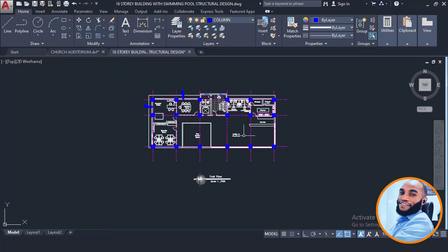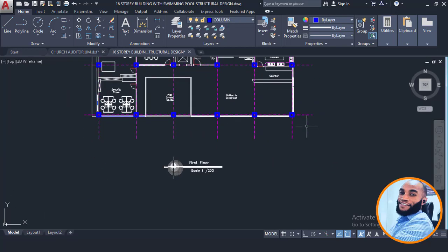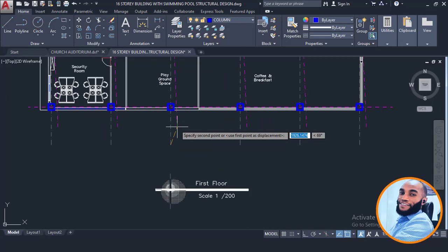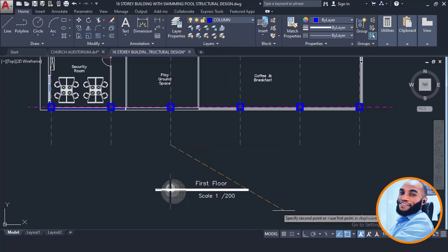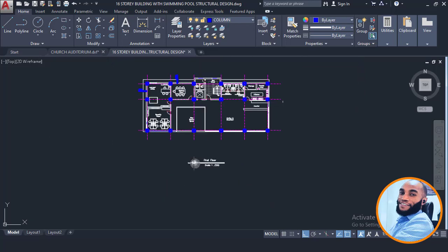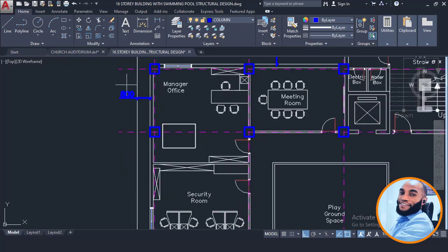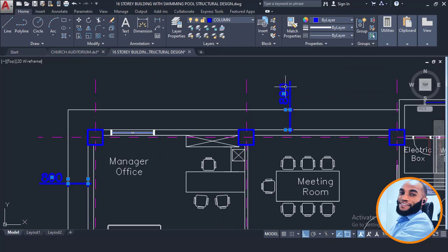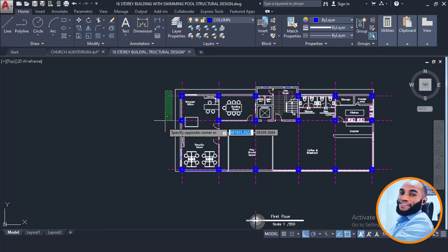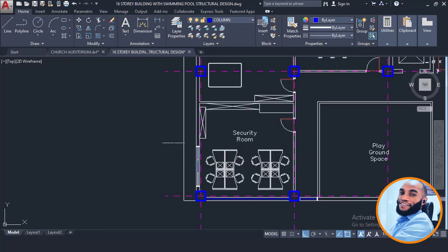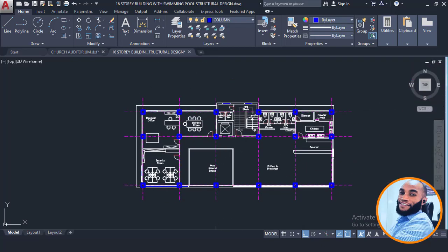Okay, that's fine. So now I can choose to lessen my grid line here by just stretching it backward, stretching this backward. Okay, I'll turn on my auto line and keep this around here. That's fine. And I can choose to remove this dimension line that is here. Take this off also. And then I can choose to stretch this out a bit from the building line. Okay, and also this one out a bit from the building.